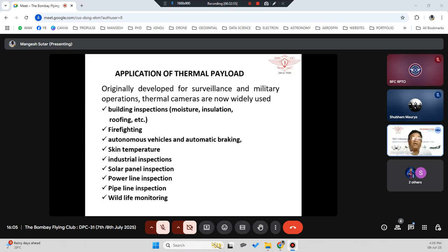So they came to know from the thermal segment which wire is good quality and which is bad quality, how to justify or how to understand. So they verified which vendor has used what kind of wires, or what type of wires are good. Then they found some trend also, like the bad quality wire that was used was oxidizing quickly or burning quickly, or because of heat they were giving a lot of problems, which is not visible to your normal eye. Okay, so this usefulness came because of the thermal cameras.